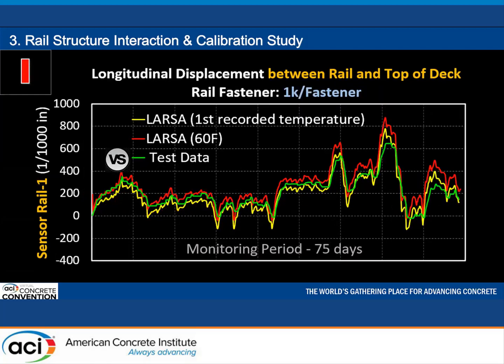How about the effect of the initial conditions of the fasteners? The yellow line assumes all the fasteners start from 0 displacement, which means each one has to overcome the fastener clamping force before slipping. The red line assumes the fasteners have been engaged, and lots of them are already on the slipping plateau. So the red line gives higher displacement than the yellow line.